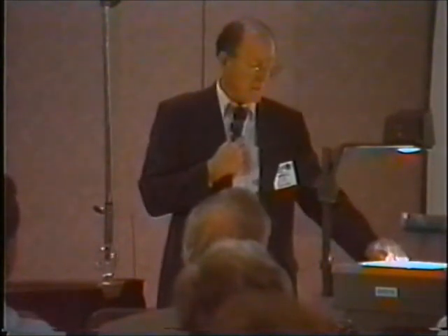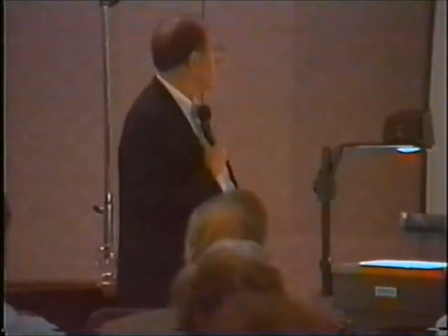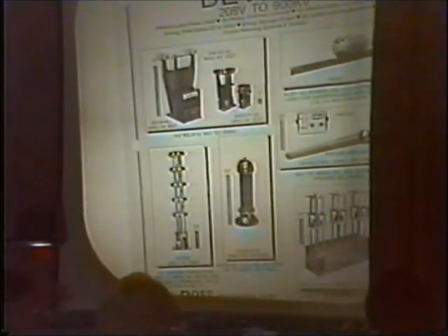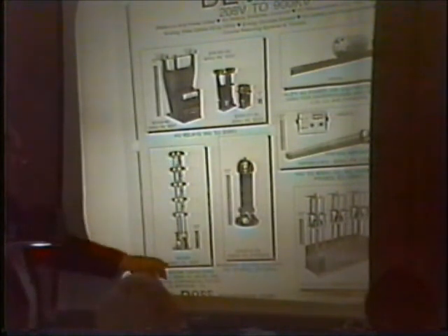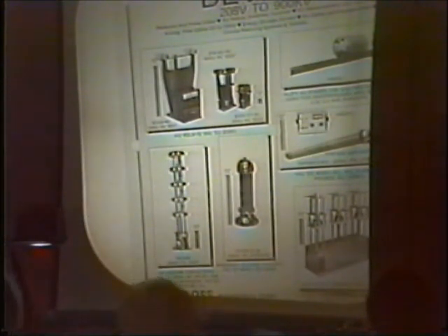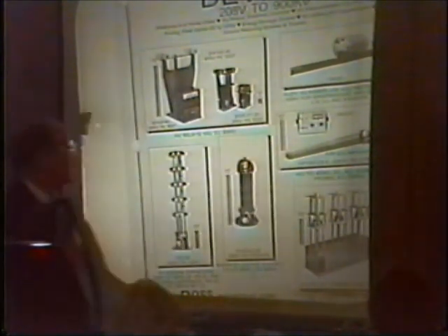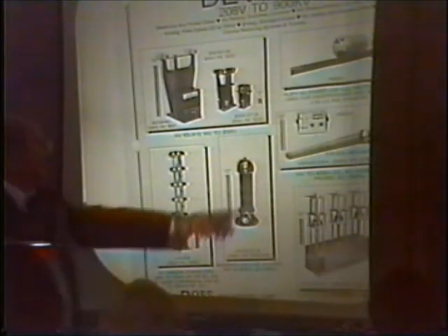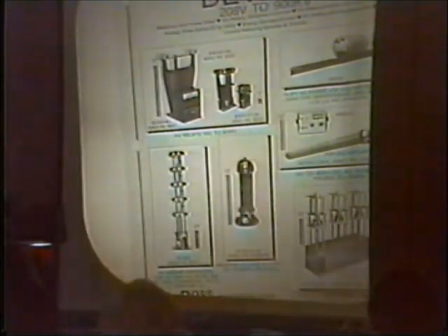Okay, here's a 200,000 volt one. You notice the 12-inch scale on there. We have a different slide that we'll see the 900,000 volt one, but you can tell that this one has a number of stages on it, and it goes to 200 kV, and this is 120 kV. These are switches, different kinds of switches. This is the instrument with a particular voltage divider that gives you 200 kV peak to work with.